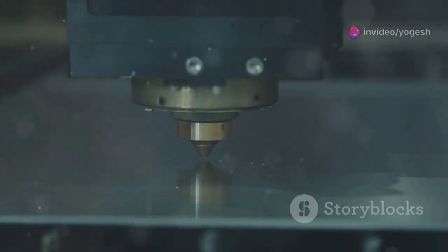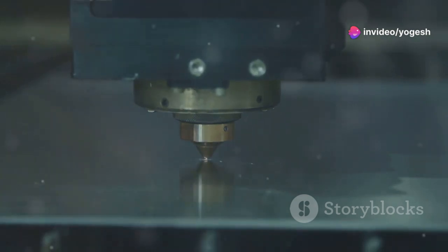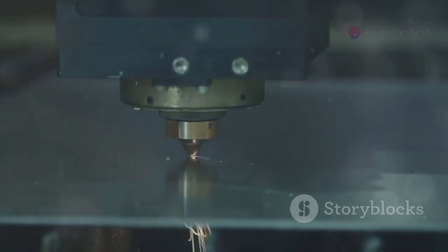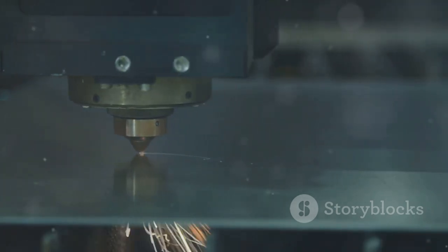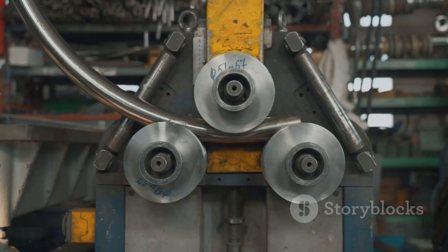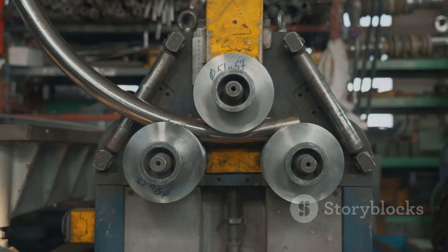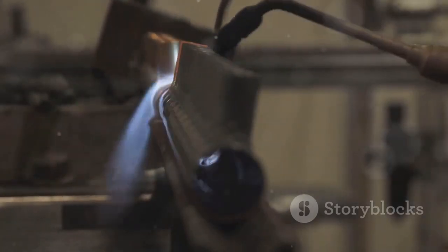Add 10 mm wide flanges at the top of the walls to support the lid. This width is well above the minimum required, providing extra strength and easier assembly. Keep all bends at a precise 90 degrees and use consistent bend radii throughout the design. This standardization simplifies manufacturing and ensures a professional finish.